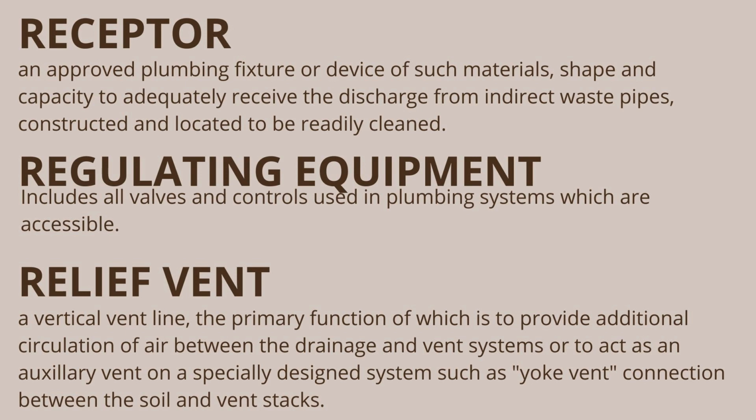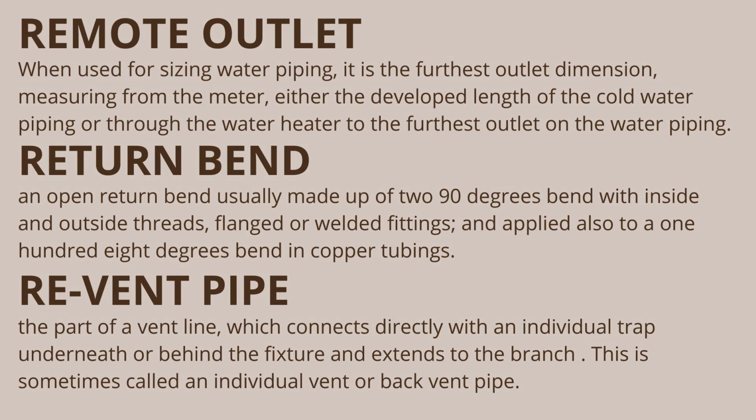Remote outlet. When used for sizing water piping, it is the furthest outlet dimension, measuring from the meter, either the developed length of the cold water piping or through the water heater to the furthest outlet on the water piping.